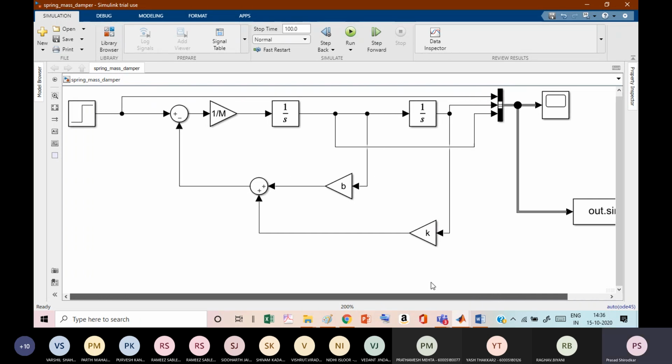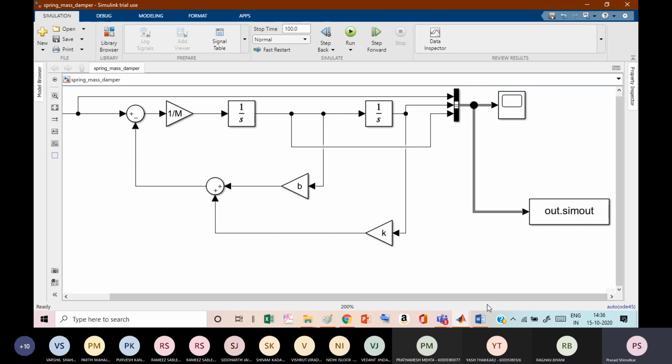How are you working out the critically damped case? So for critical damping, zeta is equal to 1. So we have to equate 2m omega n equal to c, and accordingly we have to solve. So choose some value of m, say 25. I took m 25, k 100 and b as 200.